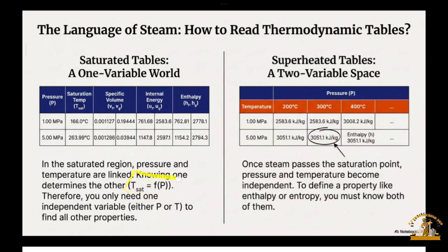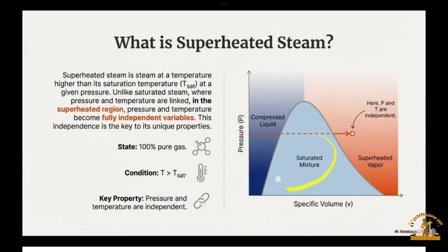We usually use this equation in thermodynamics when we know from the saturated table that the liquid in the equation or the problem is a saturated liquid, and is not yet in the saturated mixture or superheated region.